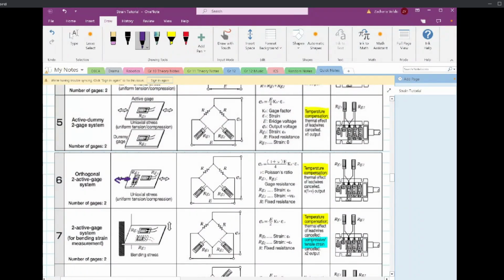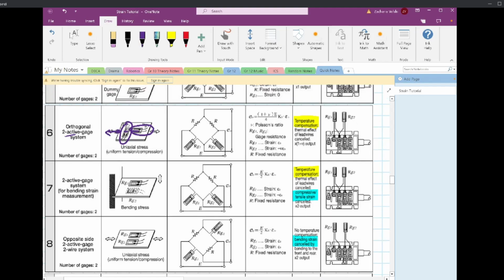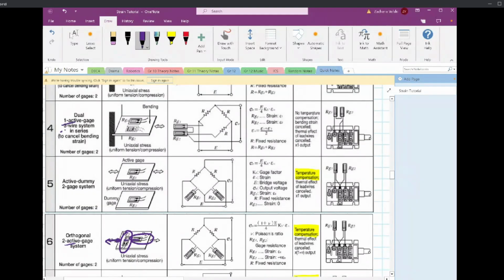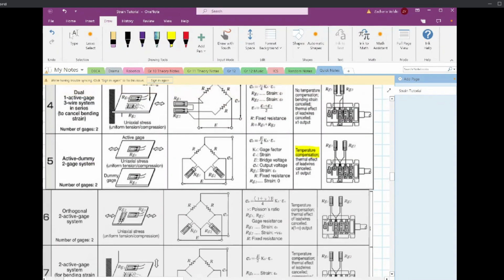This one is being loaded transversely, this one is being loaded axially. So that'll help this strain gauge to essentially act as a dummy, and this one to act as the actual active strain gauge. So that's why they say 2 active, or 3 active, 2 active, 2 dummy. That's what they mean when they say that, if you're ever referencing this table again.